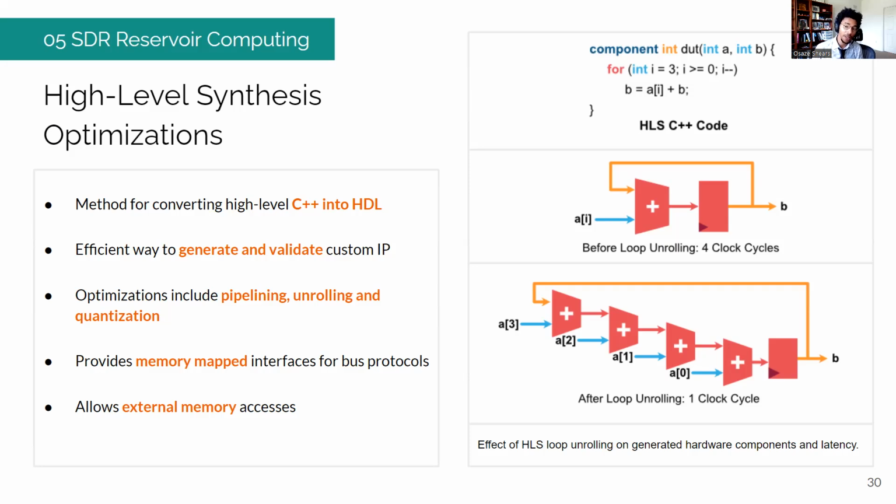But when you want to change that to the fixed point representation, which allows you to control the bits a little bit more finely between the decimal bits and the integer bits, and then create the power operation for that, it wasn't as intuitive using the tool how to go about implementing that with your own custom floating point types, or if that was even possible. So I think being able to explore the different types of quantization was a little bit tough using high-level synthesis, and that was, I think, the main challenge.